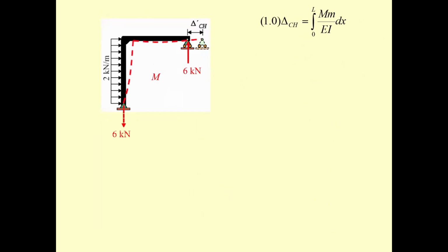So I skip the reactions, and you set up this x1 for capital M. You will use this one again for the small m. Then you may put this one for x2. That means you integrate from point A to point B for x1, and for x2, you integrate from point C to point B.